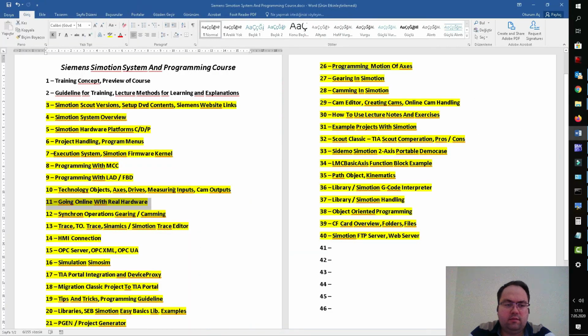So basically that's it. After the power on, the CPU is just checking when there is a need to run the fan. When the temperature rises over 45 degrees, for instance, it tries to run the fan. In this case, you got the failure and your CPU is set to stop mode with an alarm on the 7-segment display, 8. And this is the last thing related to this topic.